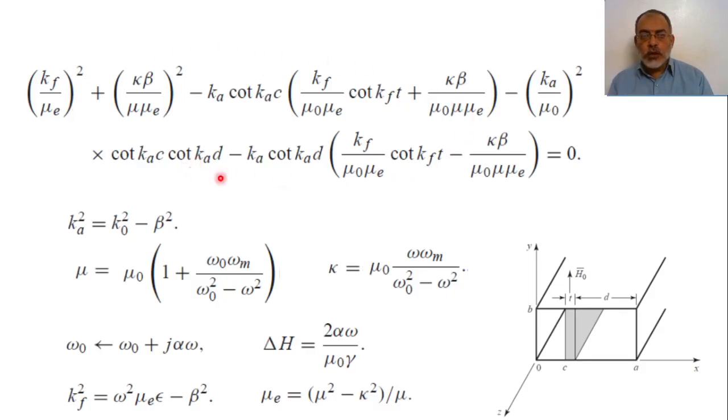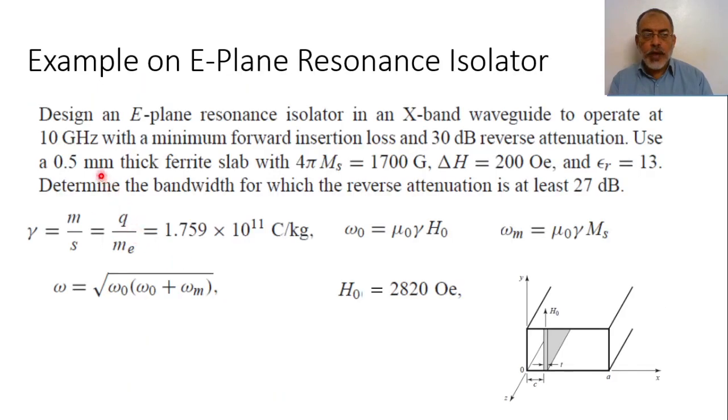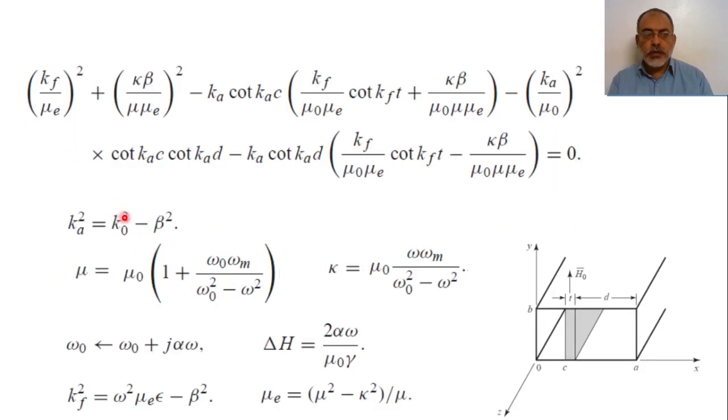For all the problem, we are going to make the frequency fixed at the beginning to be 10 gigahertz. So k naught here is omega squared mu naught epsilon naught. So we are going to replace omega by 2 pi f, and f here is 10 gigahertz. So the frequency of 10 gigahertz is included in k naught here, and is included here also. Here it is a function of omega. And effectively, alpha omega is included completely in the line width.